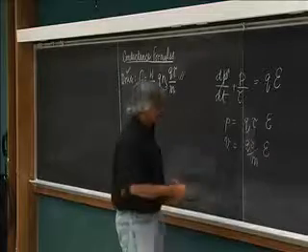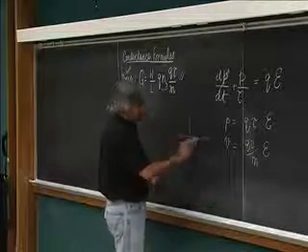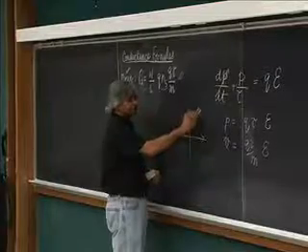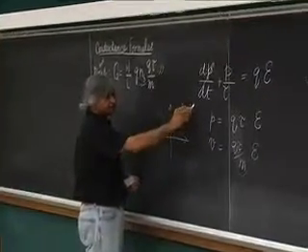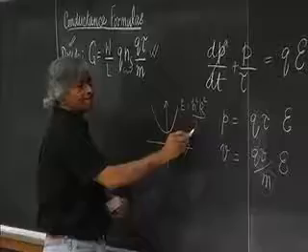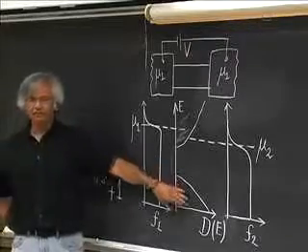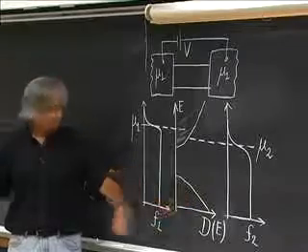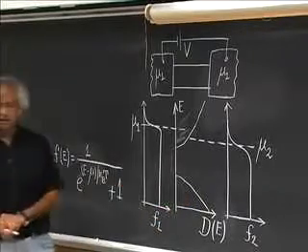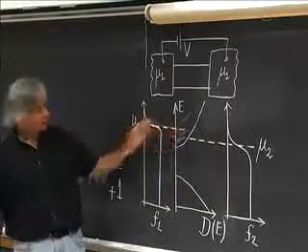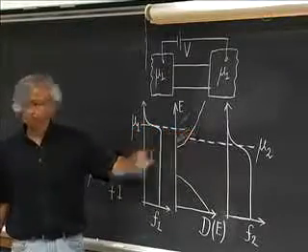Usual semiconductors have a parabolic relationship, which you write as E equals h bar squared k squared over 2m. But that's not the way it looks in graphene. And then you would have some density of states down here again. Current flows if there is a density of states available around the chemical potential.